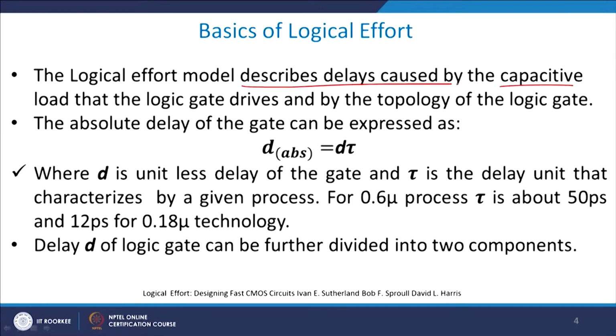Okay. So, two things which logical effort takes care of. You will have a delay because of capacitive load, right, and you also have a delay by virtue of the topology of the logic gate. This we were discussing in the starting slide, that there will be two delays associated with any design. The first delay will be the intrinsic delay, which is basically because of the device, because of the capacitances and so on and so forth, right. Whereas the second delay depends upon the logic structure which you are using. Are you using NAND logic, are you using NOR logic, what type of universal gate are you using in digital logic in order to express it.